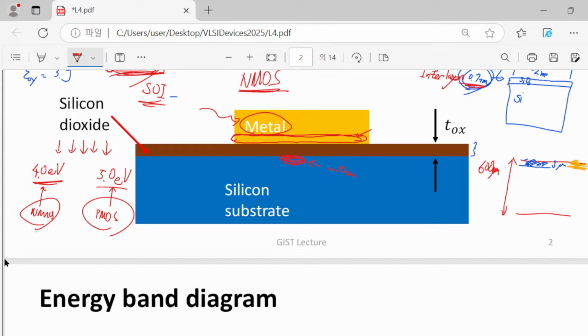What is the difference between them? If we go to the low power version of these transistors, then in the case of N MOSFET, the threshold voltage increases. Since the threshold voltage increases, at a given zero gate voltage, you have a lower leakage current. Therefore, you have a standard one, low power, ultra low power. This is just 3 different versions, but in between we introduced many others.